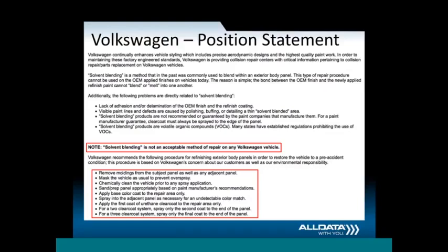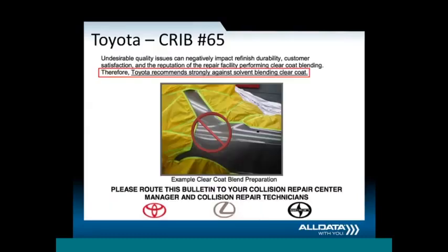You also see here that Volkswagen has a statement that says we need to remove moldings and not sand up next to them or tape around any of those, because it could cause a delamination problem. So bottom line is, if I replace or repair a quarter panel, I would legitimately put on my estimate that I'm going to extend clear to the natural breaking point. If it's a Volkswagen, for example, I have a bulletin that supports that what I'm doing is according to the OEM. Toyota is another manufacturer that says the same thing. Toyota recommends strongly against solvent blending of clear coat, and you must extend clear to the natural breaking point.